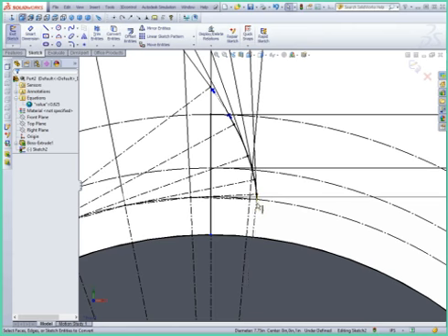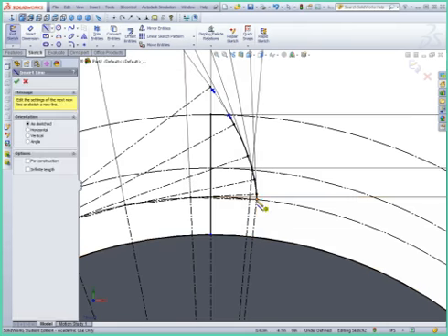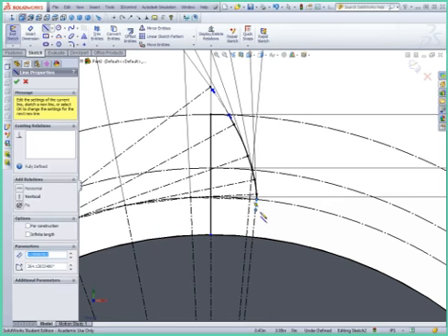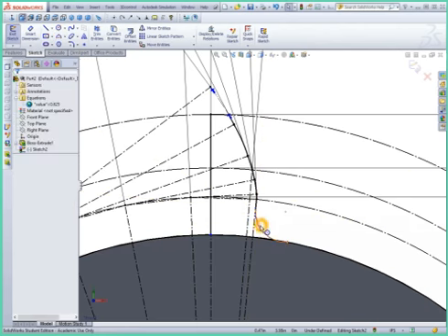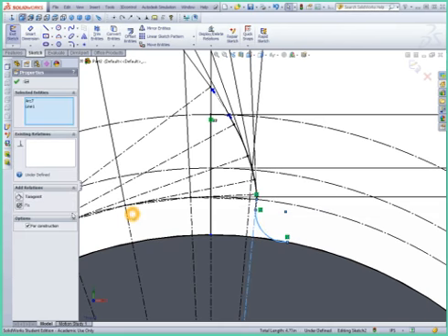Generally what happens is you go down a little bit and then you have a radius here. One of the things we want to make sure is that the radius doesn't intersect with the next tooth profile. So I will draw a short segment here, and then I'm going to draw a 3-point arc that connects that segment to our dedendum. I'm going to force that arc to be tangent to both surfaces.